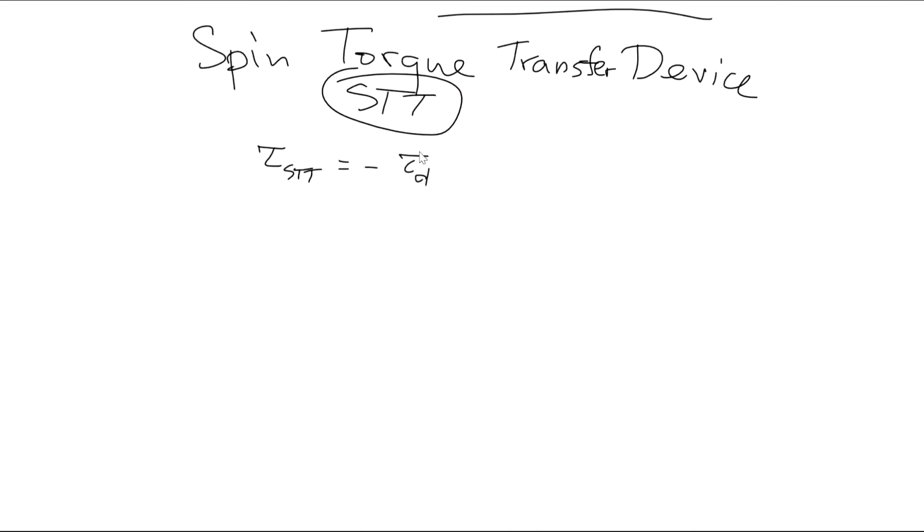And to do that, you need certain current densities. And as Slonczewski calculated in his work, by the way, this was work done in 1996, you can dig up his paper, current densities should be around 10 to the 7th amps per square centimeter.